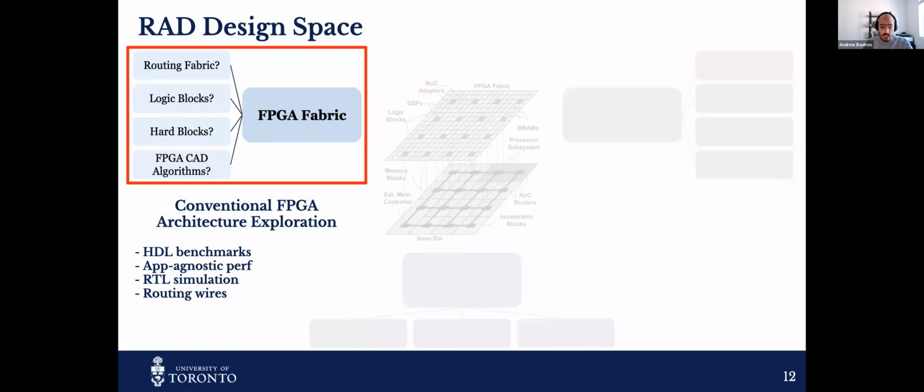basically what you do is that you describe an FPGA architecture that you want to evaluate, and then you write a bunch of benchmarks typically in HDL, Verilog or VHDL, and then you run it through the VTR flow, which does the magic of mapping those benchmarks written in HDL to the candidate FPGA architecture, and tells you, okay, here's the area of this FPGA, and also here's the clock frequency that you can basically run this circuit at.